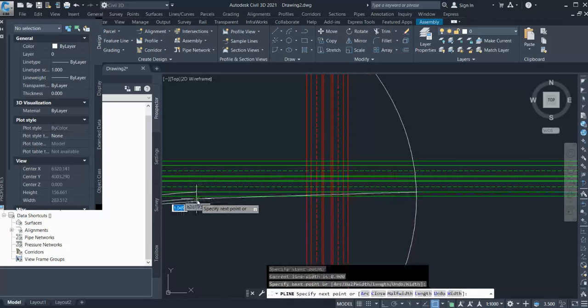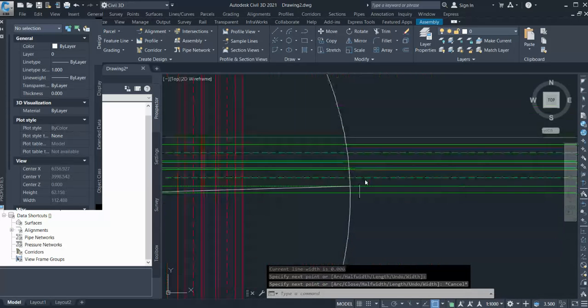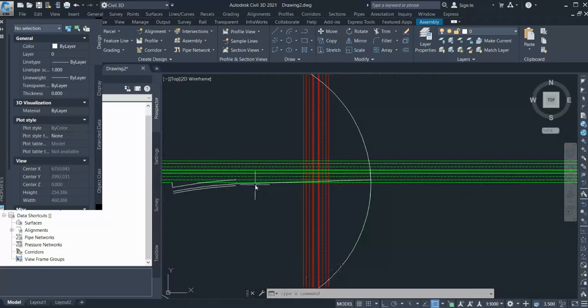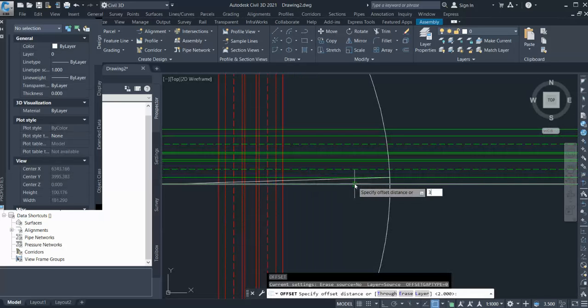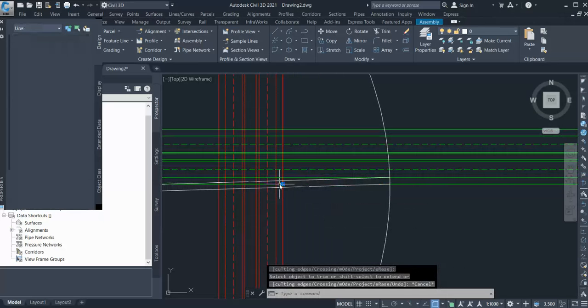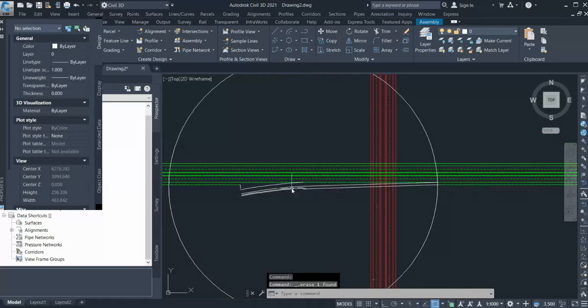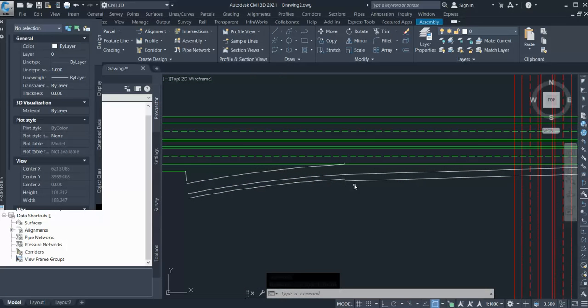So I'm just giving a 150 meter diverging taper, and from this up to this diverging taper, your hard shoulder width would be similar to your main line. So I'm going with 3 meter hard shoulder, deleting this, and whatever the difference between the two hard shoulders would be tapered in this nose area.